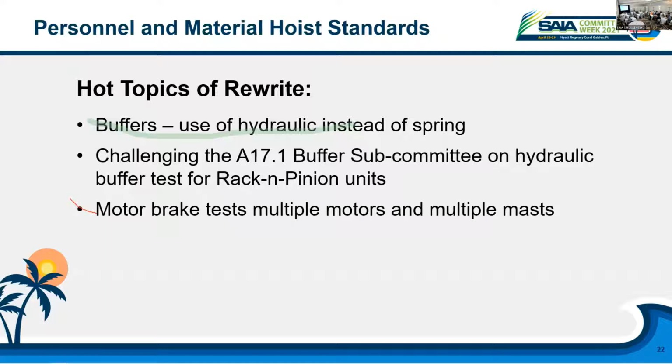Next is motor brakes test for multiple motors and multiple masts. We're now having larger personnel hoists that have dual mast systems, multiple motors to handle the loads. Well, now we have requirements for motor brakes. And how do we test those motor brakes? Are we required to have every motor brake handle that load? Because I don't know of a motor manufacturer or brake out there that can handle the full load of the machine by itself. So what's the correct combination for testing these machines? Nothing really goes past 2 motors in the standard right now.